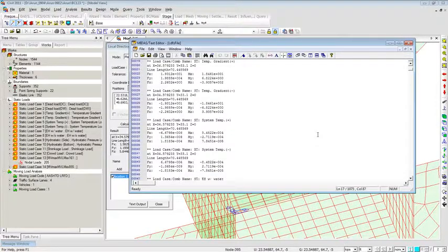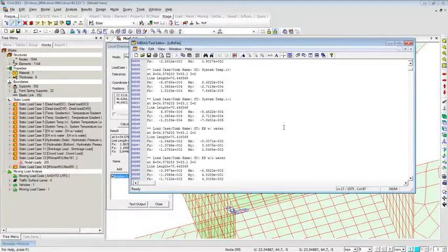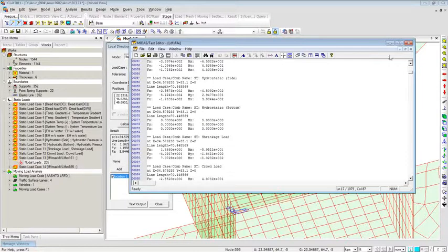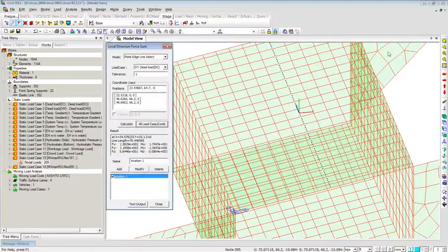So you can select your critical sections, cut across that plane, and let the program calculate the design forces for you in no time. And once you have these design forces, you can go ahead and use any kind of design tool that you prefer, like spreadsheets or your own set of written MathCAD programs to quickly get the design done. So this covers the third point that I was saying, that how easy the result extraction can get.